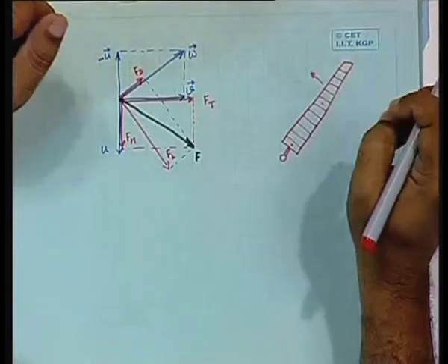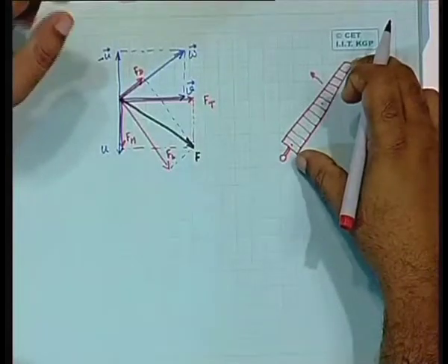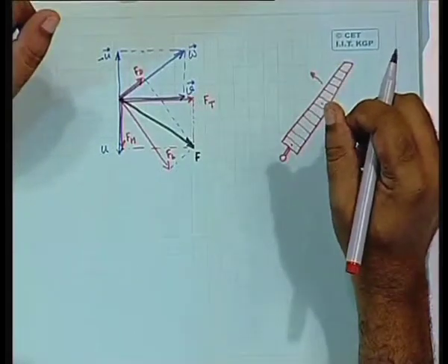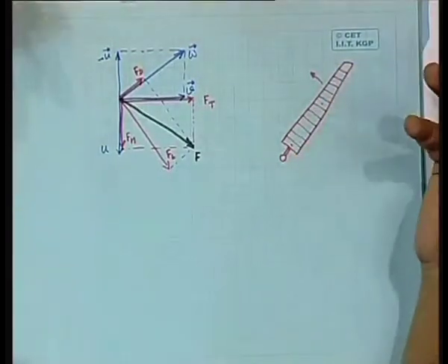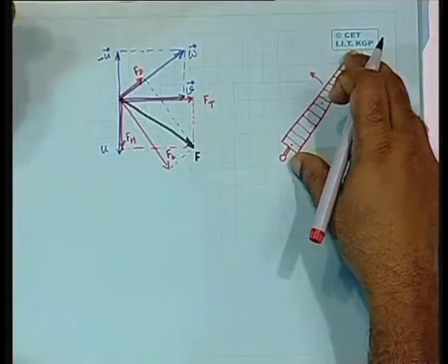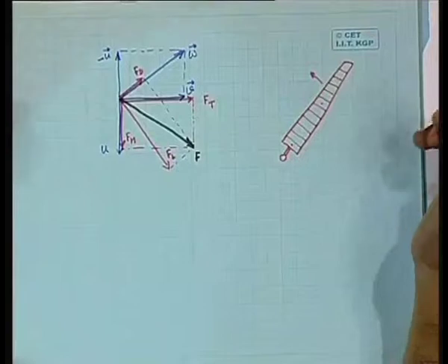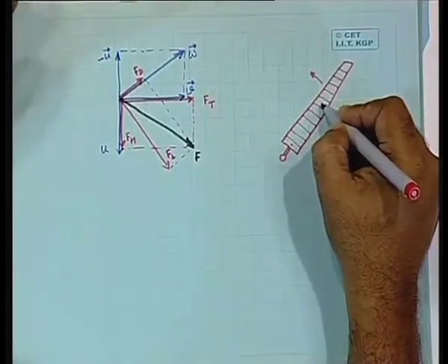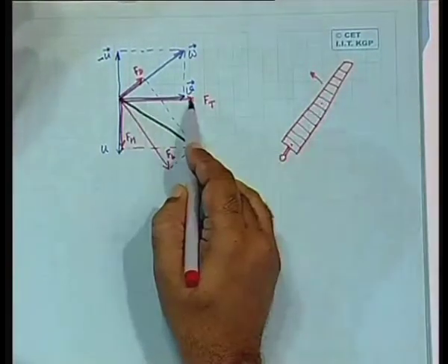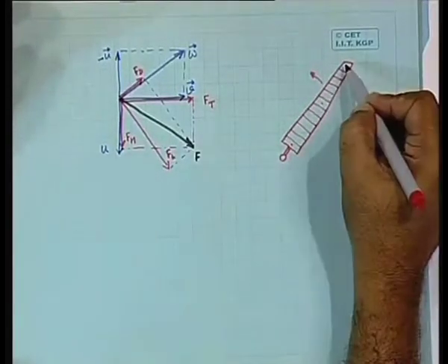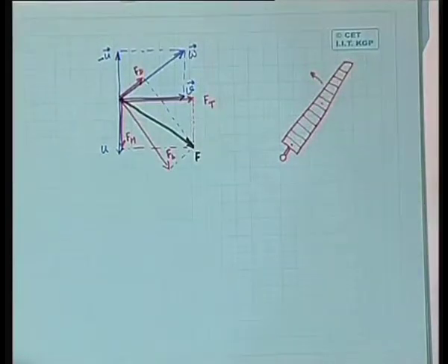While doing the calculation by hand, we often divide the blade into a small number of sections, say 3 or 4, and we can do the calculation by hand. But often the actual calculations are done by computers, where you define these into many small sections, and for each section the calculation is carried out, and then you can add up. For example, if this one produces a certain amount of thrust, this force, this one produces another certain amount, the whole thrust experienced by the blade will be simply the summation of them.